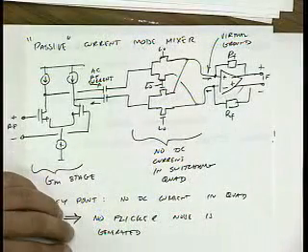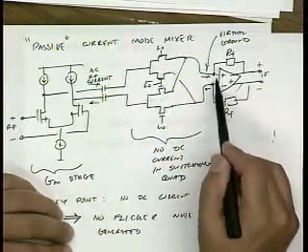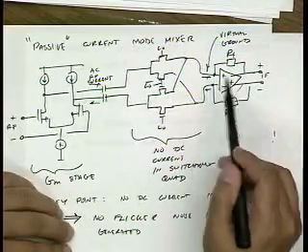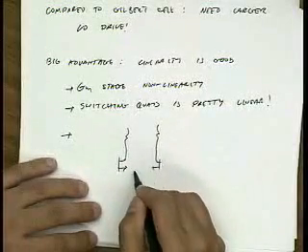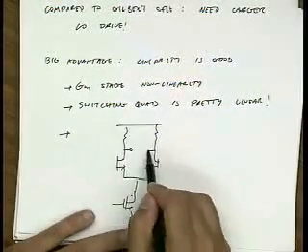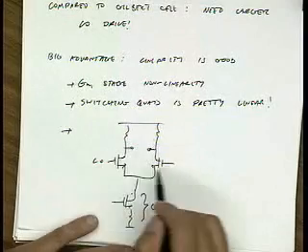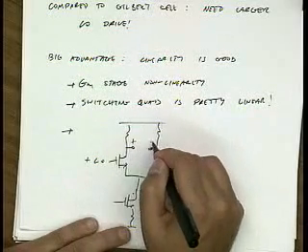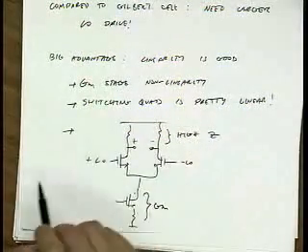Now in a Gilbert cell mixer, if you think about it, the output would be a large resistance. It would be a high impedance load. And so there would be a substantial voltage swing at the output. And we would have a big problem because that is on a low power supply voltage. So let me draw a picture. Let me just draw half of the Gilbert quad. Let's say that we have the same GM nonlinearity here. That's comparable. Let's say we also have the same kind of nonlinearity through this LO stage, but then at the output here we have a large voltage swing, right? And so that will generate nonlinearity in the transistor. It'll limit the voltage swing.